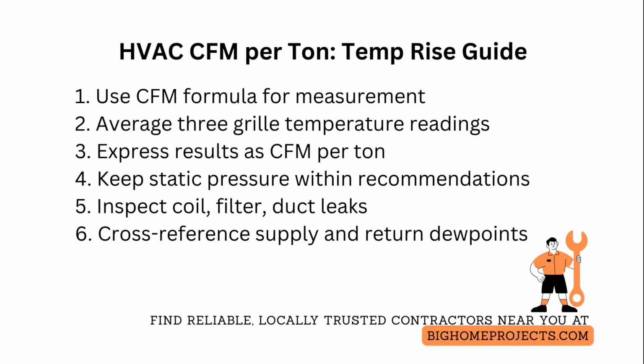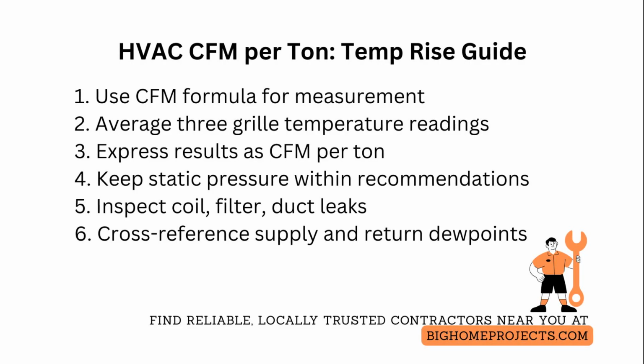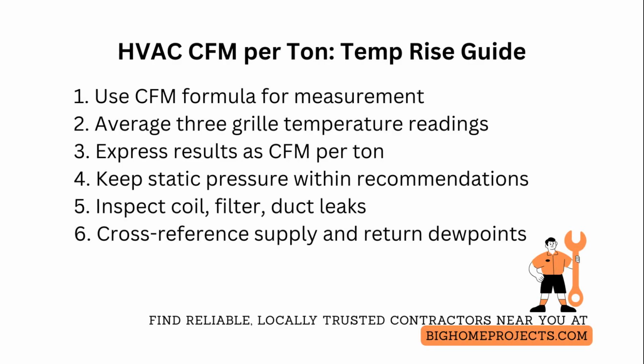Lower values around 300 to 350 CFM per ton increase dehumidification but can cause coil freeze risk if evaporator temperature drops too far. Higher values near 600 and above reduce dehumidification and boost sensible cooling, potentially leaving relative humidity too high for comfort.